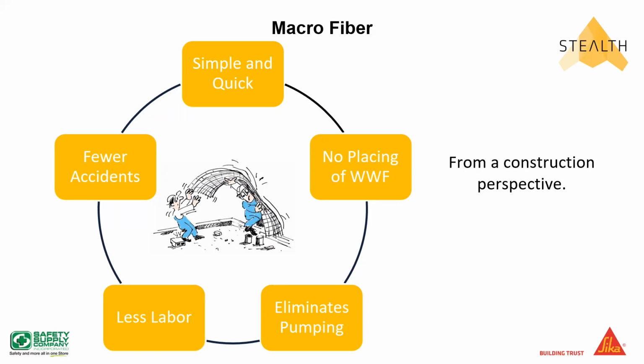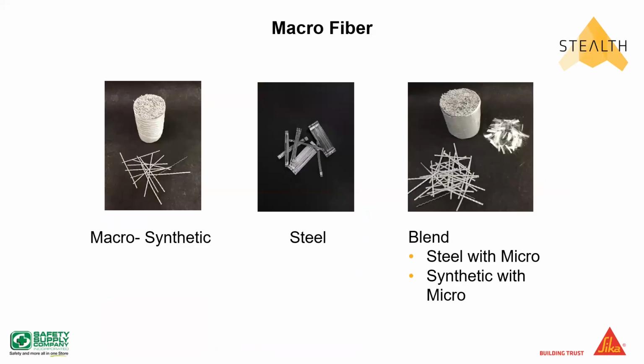Like I said, the integrity, whether it's for just crack control being a microfiber, or structural integrity and crack control being a macrofiber. Again, it's coming in the truck. So when the concrete goes down, so does the reinforcement. So anyway, those are the things that you'd be looking at from your perspective.